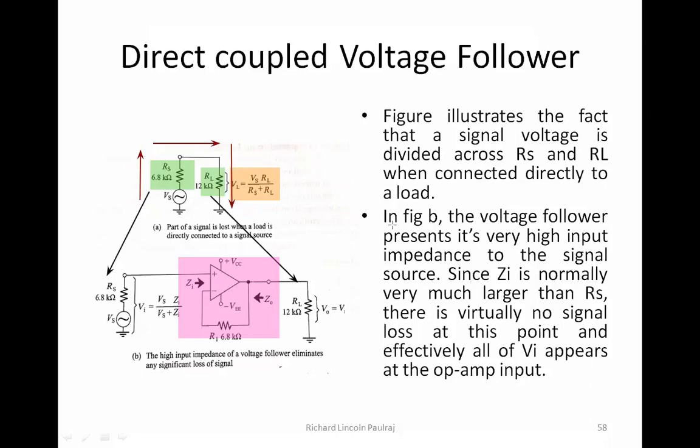Is it blocking voltages or is it blocking currents? Current, sir. Very good, right? So when I say high input impedance, it's not allowing any current. Okay. When I say low output impedance, it means that there is very low resistance, so it can just flow through.